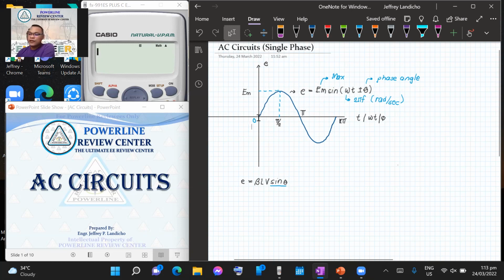So in this illustration, I placed our waveform at the origin. In this case, the phase angle is what? Zero. Now, when will it be positive, and when negative? So we have a waveform that starts before the origin. Let's say this is the waveform we need to consider. Assuming for this given waveform this is our starting point, when we take the distance between the starting point and our origin, this is now our phase angle.